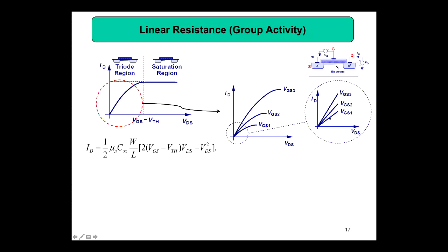Now what I'm going to find out is the resistance value from this equation, because here you got ID, then you got VDS. So then we can find out the resistance of the channel, because previously we knew that it is a voltage dependent resistor, but we didn't know the value, what equation we can use. But now because we got ID and VGS, VDS, all these things in the equation, we can find out ID by VDS or delta ID by delta VDS. If you find that out, you are getting the resistance across this channel in terms of width, length, mobility, capacitance per unit area, VGS, so all the parameters are already taken into account. So when you find out, it is easy.